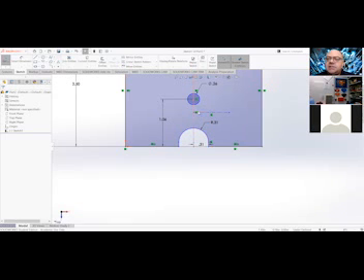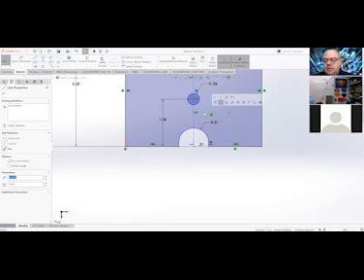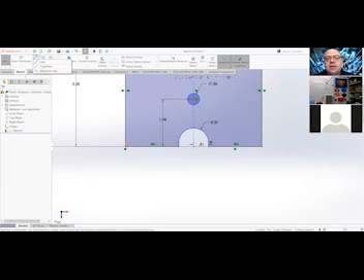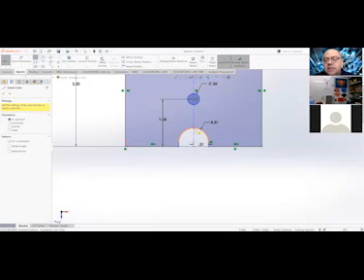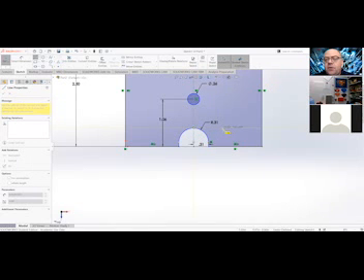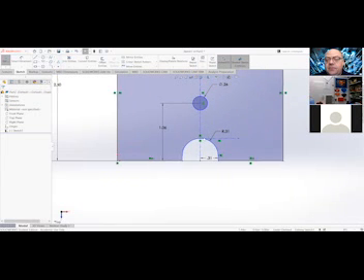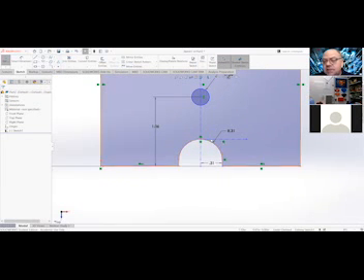If I can do that, a center line to center line, I'm going to take that one off for a minute. Then I'm going to do another one from the quadrant of the circle and pull that left or right. Just make sure it's horizontal. Now, when I get down here, I've got a horizontal constraint, I've got a tangent constraint, and I've got a tie down constraint. So I've taken this center line and I've tied it to the arc, okay?